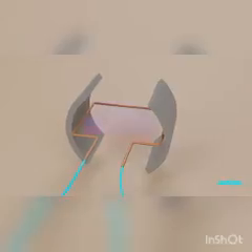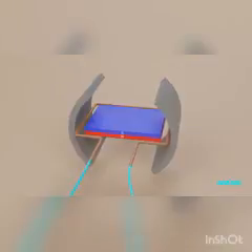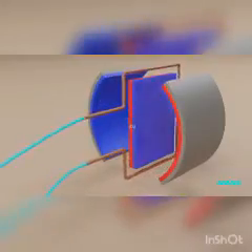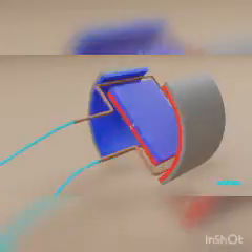This time you can think of the electromagnet as flat like this with the south pole pointing up. Now the armature will spin until opposite poles are lined up. We can keep it spinning by switching the wires just like we did before. But this is a lot of work to sit here and manually switch these wires. We need to add something to the armature called a commutator.